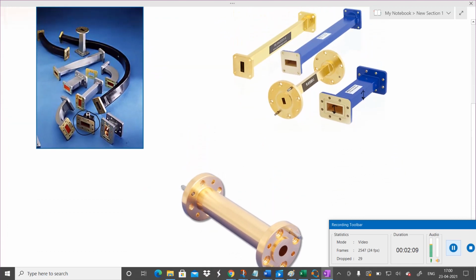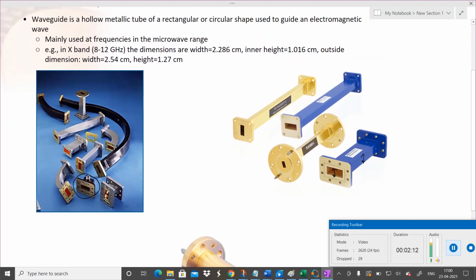Now our main aim in this lecture will be, if we transmit any microwave at one end of this waveguide, what is the relationship of frequency? I mean, which frequencies will it allow? Will it allow any frequency? We will see that after solving the Maxwell equations. Definitely we have to solve Maxwell equations when we are transmitting electromagnetic waves through these waveguides. It is not that for a given dimension of waveguide any signal will be transmitted. Depending upon the dimensions, there will be particular frequencies which will be allowed to transmit through the waveguide.